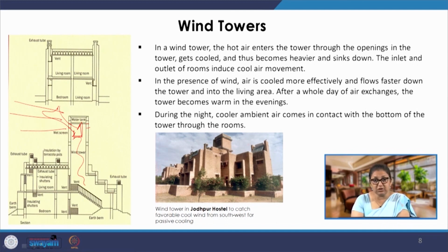Again, the wind tower is a feature that we are going to use for warmer climates. So, there is this thermal mass around. The walls of wind towers are going to be thicker, and this mass will absorb the heat from the air coming in from the top, and it will settle down. Sometimes it will work like that. If we do not want to do that, and we provide the opening on the opposite side, the wind only takes away the heat. In the first case, we will provide windows here at the bottom, so that the cooler air is entering into the rooms.